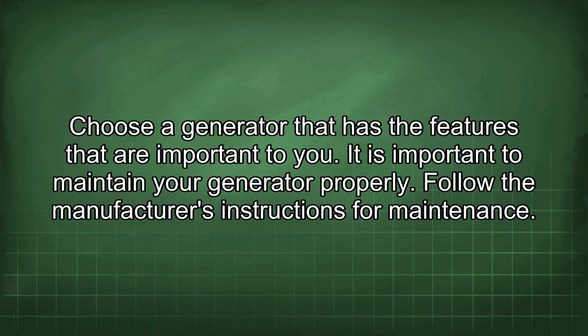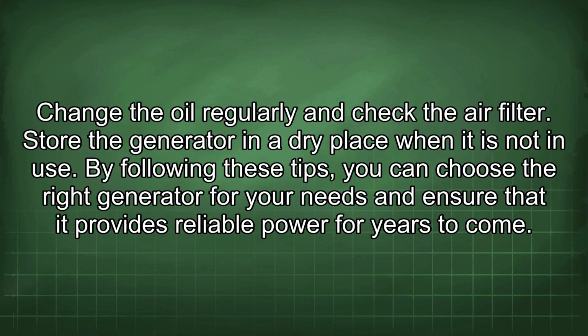It is important to maintain your generator properly. Follow the manufacturer's instructions for maintenance. Change the oil regularly and check the air filter. Store the generator in a dry place when it is not in use.